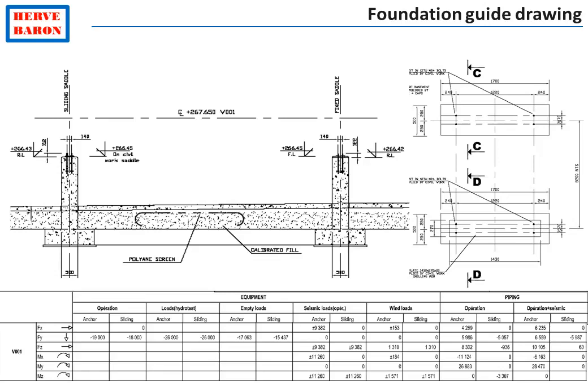The civil engineer of the EPC contractor does not always perform the design of foundations. Indeed, the design of foundation has to be by law compliant with the local code where the plant is being installed. And the EPC contractor civil engineer is not always familiar with this code. Therefore, it often employs a local engineering office to perform the design of foundations. In this case, the EPC contractor civil engineer stops at a guide drawing, such as the one shown here, which shows the equipment setting plan and the loads. In other words, all the input data.